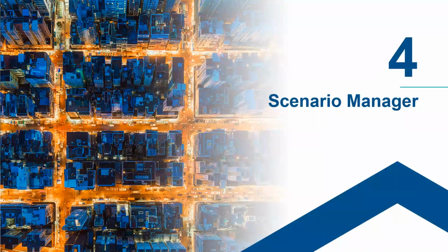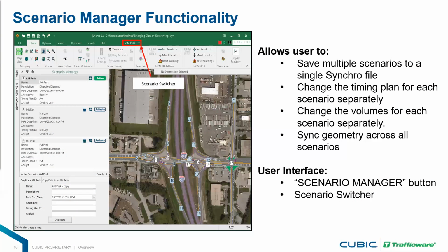Okay, so the next thing I'm going to talk about is Scenario Manager. Scenario Manager allows you to have multiple scenarios in a single Synchro file. So with Scenario Manager, you can save multiple similar scenarios in a single Synchro file, which will allow you to reduce the time of managing so many different files with the same network. That's a very big benefit of Scenario Manager.